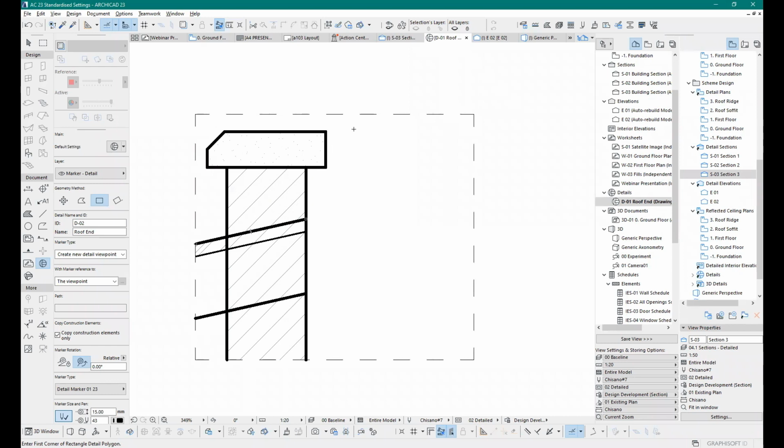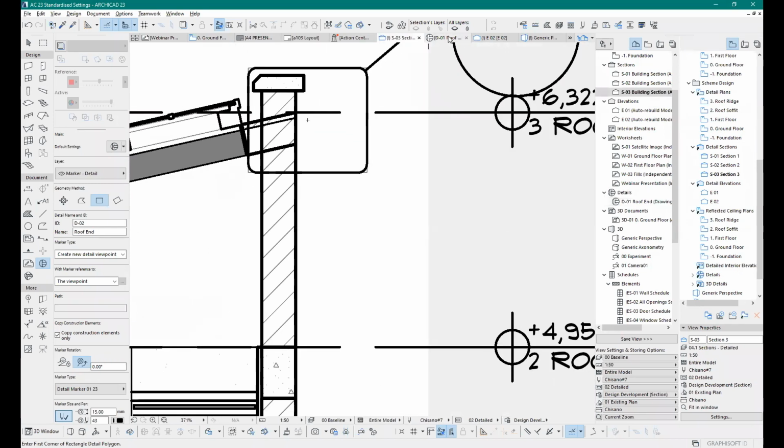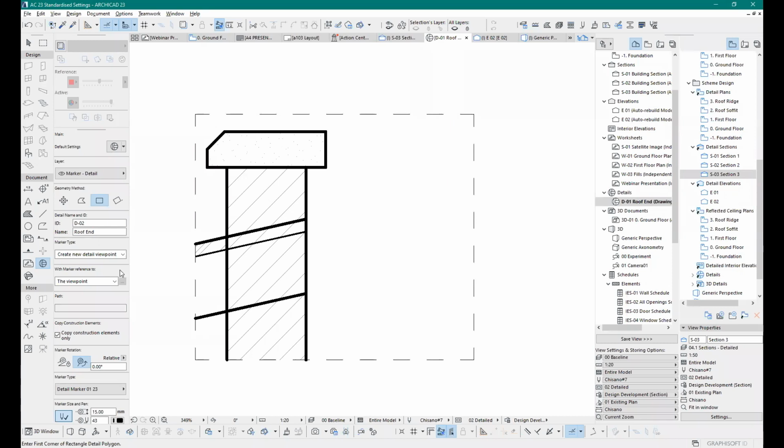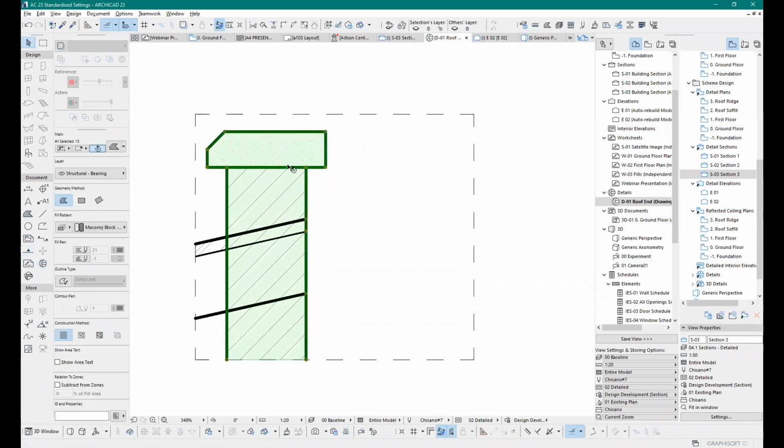Once you create details, it explodes the building materials into fills and lines. So the cut fill pattern that you see here becomes just a cut fill. If you select, you'll see that all this is a fill that's been selected. And you are able to select bit by bit by suspending groups up here.